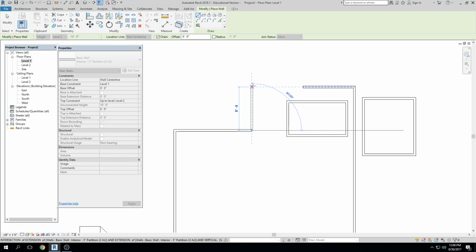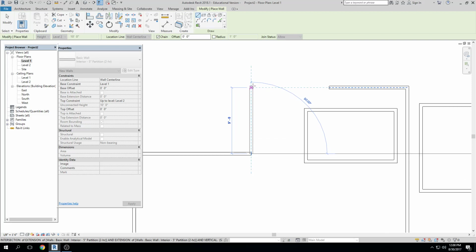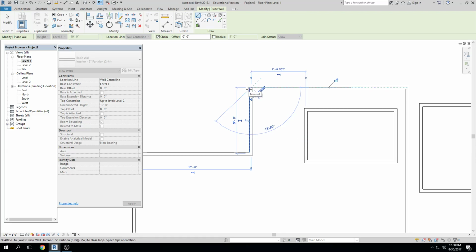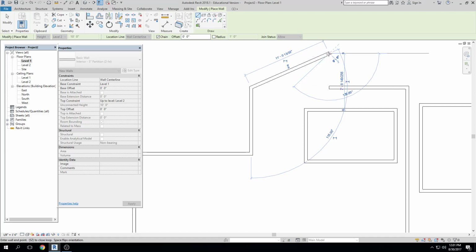on other objects, okay? We have a kind of simplified version of that in Revit, where you notice that as I move in the direction of this line, you see how it lines up with things, right? So if I want to line up with this wall up here, I just get up to wherever it's at and it lines up and I click, right? If I want to come over here and line up with it, maybe in the vertical, I just hover down and touch it. I don't click, but I hover down and I touch it, click. And it shows me where these objects are. And you see that's an endpoint and it tells me if I hover.